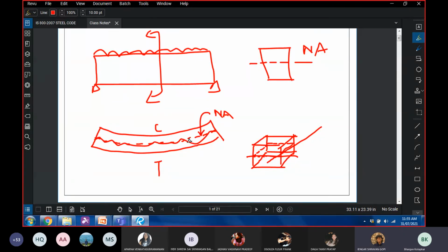Because concrete is not fully homogeneous, the plane will be more uneven in concrete than, let's say, steel, which will have a slightly less uneven plane. So it is a theoretical axis, a theoretical plane, but practically also there's going to be an axis that will never have any stress, that will not have a stress under that particular loading. That's called the neutral axis. Thank you.